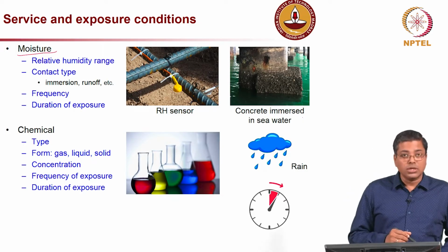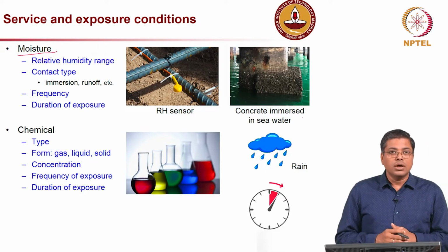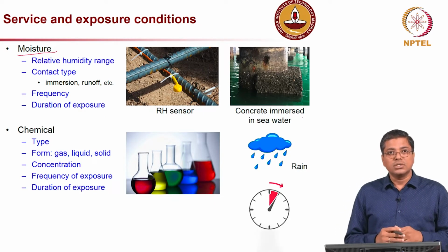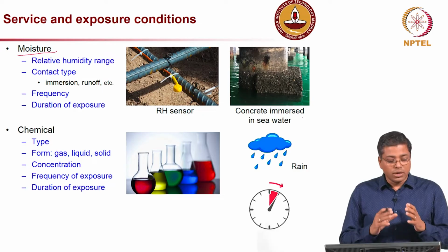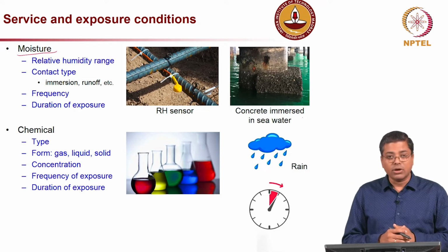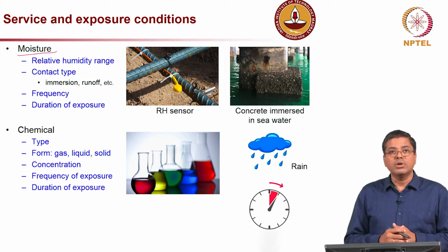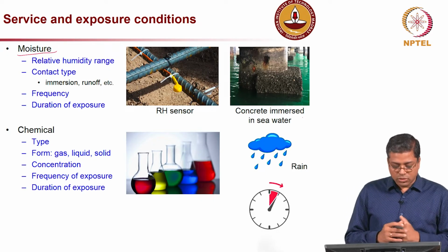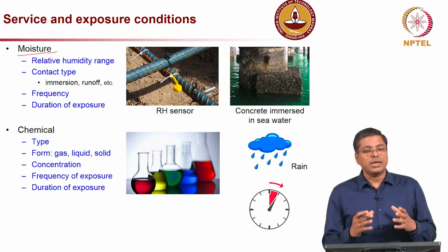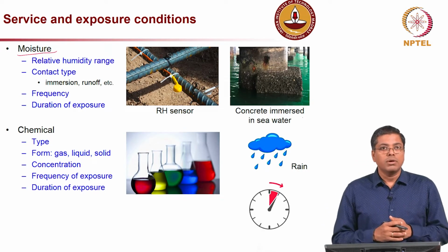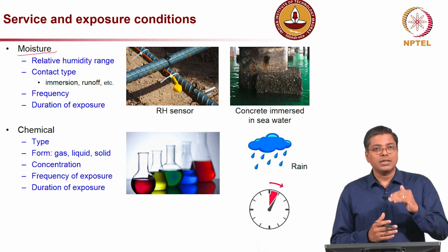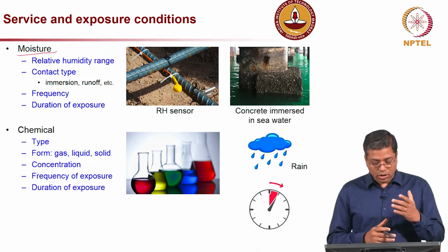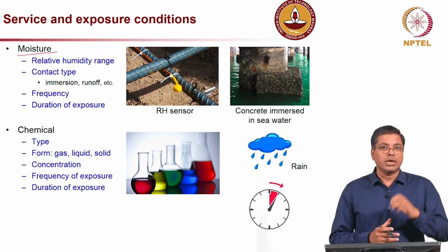That is very important to know, because the corrosion phenomenon depends heavily on the moisture conditions, especially in the cover zone or, in particular, at the steel-concrete interface. There are some humidity sensors also available in the market today. So, you can use all that to get an idea about how much is the humidity level at the steel-concrete interface, because if you want to really assess the corrosion mechanism, moisture condition